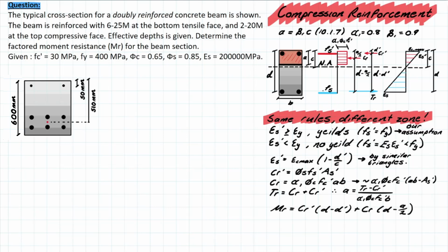So, what we already know about reinforced concrete beams is that if we wanted to make them stronger, we can do a couple of things. The first thing we can do is add steel, obviously, to that tensile bottom face in order to provide that steel strength rather than relying on the concrete. The next thing we can do is look at the geometry of the beam. We can either increase the width or we can increase the depth. But obviously, the more effective approach would be to increase the depth because it will give you a bigger arm between your couple moment produced between the CR and the TR, right?